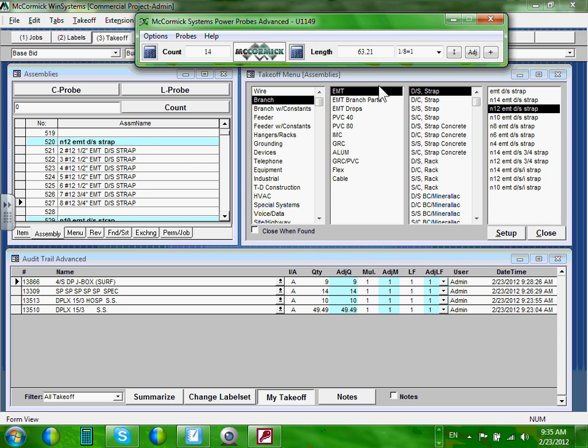So sensitive. Can you guys see the scale? What's the scale that's set there? 1/8. So important to set your scale right. If my scale is wrong, you just go over here, where you set the scale, and change it. I think the scale that we were using is 3/16. The scale that I'm using is 3/16.